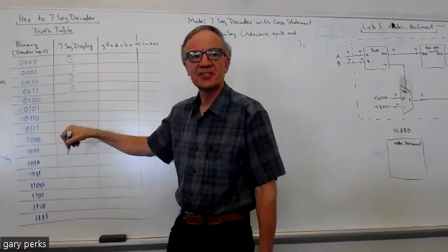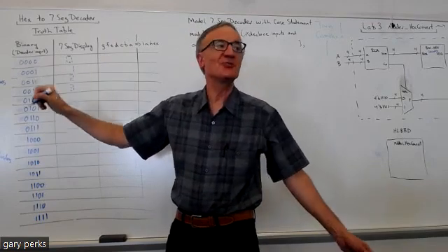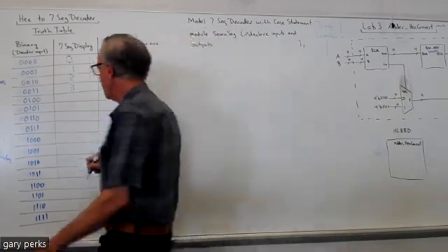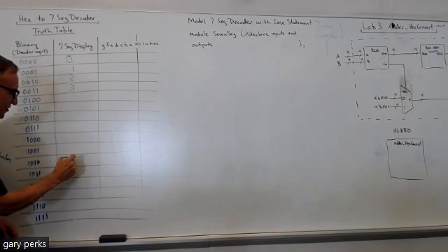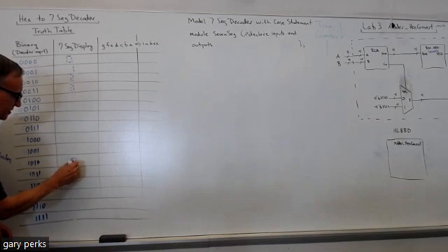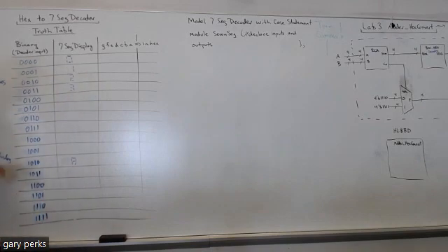And you just keep filling in. I'll let you, unless there's one you want me to do. But once we get to a binary 1, 0, 1, 0, what do I want to light up, since this is a binary to hex converter? Yeah, you want A, because 10 in hex is A, right? So here you'd want a capital A. Right, so you light up everything except D to get a capital A.